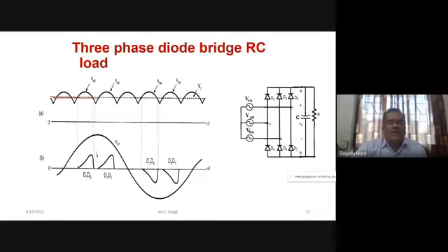We represent this with the dotted line. I am just drawing it here. So this will be our output voltage across the capacitor, the average of whatever we have. So it will be a smooth DC voltage appearing across the capacitor. Now, because of this capacitor voltage, let us assume VAB and VAC. For VAB, which devices are conducting, A and B? It will be device number 6 and device number 1 conducting. Here device number 1 and 2 are conducting.